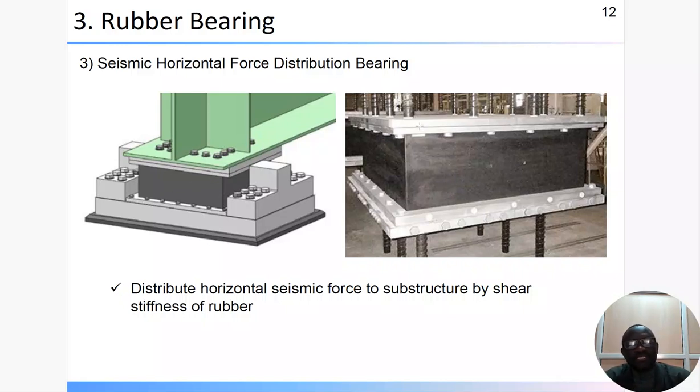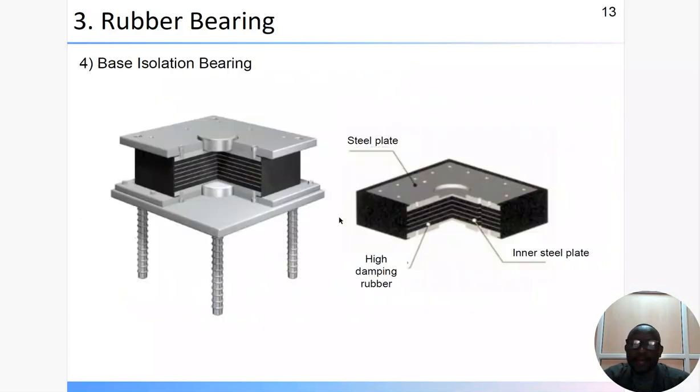When you're modeling, you can see a rigid link up from the top of the slab coming to the bottom. Then there is a connection here with the elastic link. This is now the one, and the stiffnesses you can calculate when you design and you calculate that. You can now compare the calculated stiffness. Then you compare with what it is here. If they match, then you order the bridge. If the plan dimensions are okay and the stiffness is fine, then you should be able to do that.